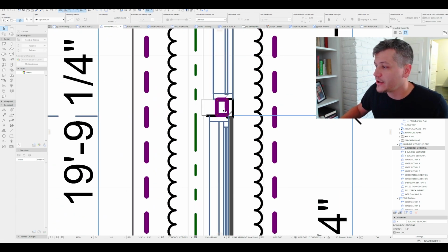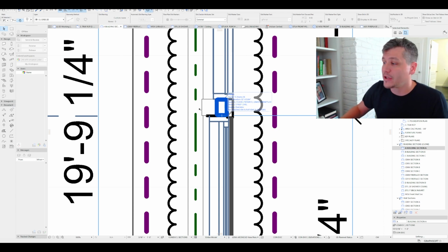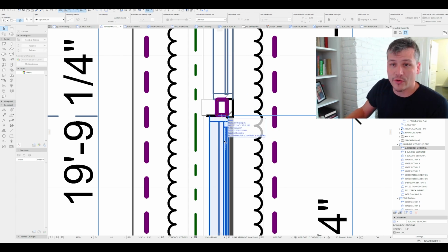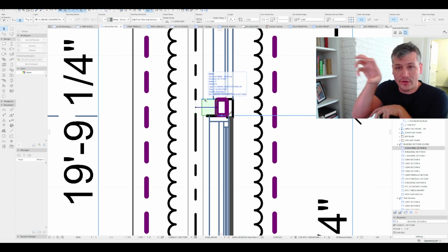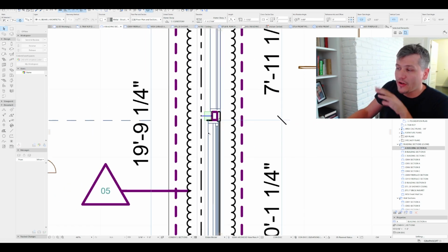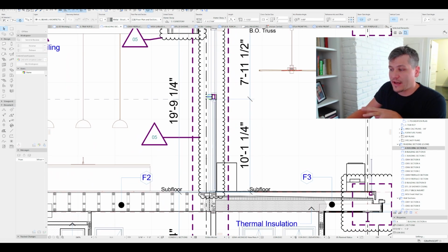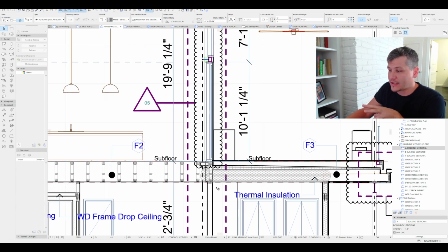So there's a header here that's supporting the window on the top, and then below is, of course, the big sliding door that makes up that glass wall. And then there's this little metal element that sticks out and actually grabs onto that header. But all of that stuff needed to be detailed out, and it needed to be coordinated very heavily with the window manufacturer.